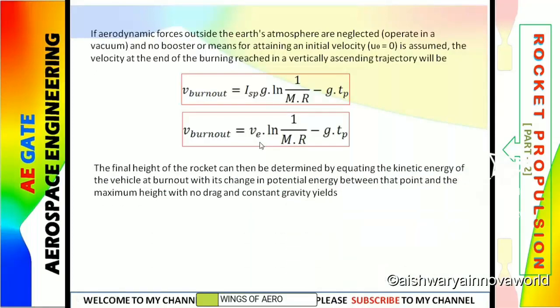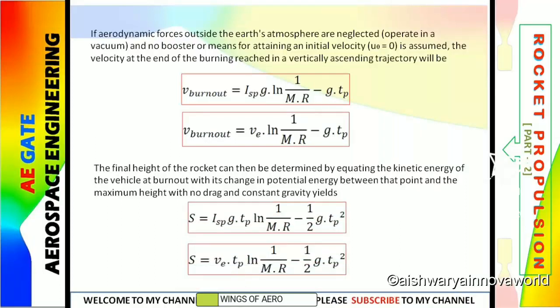Now we'll see at what height it can gain in the vertical flight at some particular given burnout time. So this is a formula. This is another important formula. See how you can remember this formula. I will tell you very simple tricks. Already you know this value is our ideal rocket equation. When you are using the ideal rocket equation for vertical flight, we are adding an extra term, that is minus g TP.